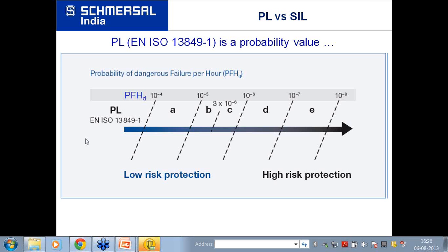Mr. Rajesh Mohanan has asked how many layers of redundancy, two or more, of safety systems are generally recommended in automated systems where accidents can lead to irreversible injuries to personnel. There's no thumb rule on how many redundancies you should have. This should be a requirement from risk assessment.